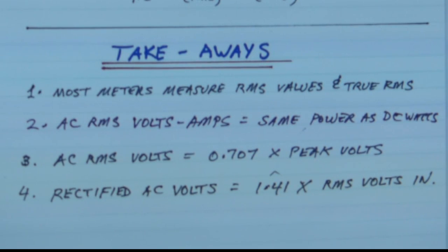So when you're looking at an RMS value of 120 volts, and you plug your leads into a power outlet, realize that the 120 volts is an RMS value, and the peak voltage of that circuit is higher. It's going to be upwards of 160 volts or so. So watch out, because that's why it bites, as Radar says.